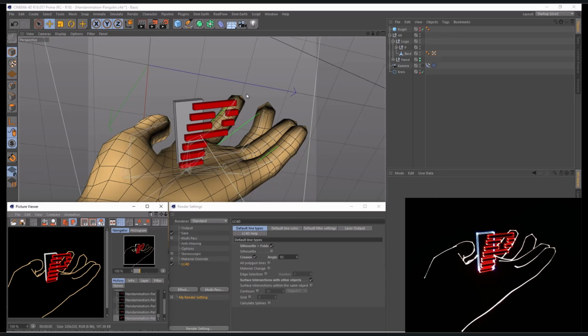And looking at the current output, the current points calculated of this frame is, without any optimization by the way, 1684 points, and it is scanned with a scanning speed of 45K pps. And this means even at this high speed, running on quite fast scanners, the output is far away from considering it as flicker-free. This means the animation is not really nice, and we should now directly start with some first optimizations.